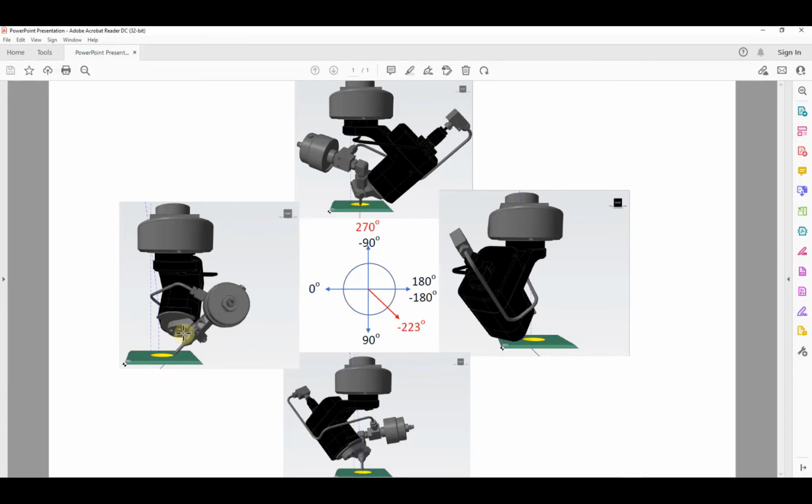So you want to avoid singularities, and that's why you should always do tilted piercing, because if you start piercing vertically and then the cutting head tilts over, there's a pretty good likelihood that you could pass through that singularity point and it'll spin around and ding your part. So that's why you always recommend doing the tilted piercing with the Apex 60.